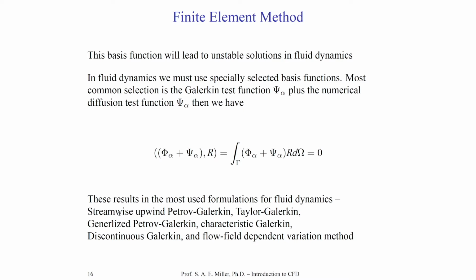That means that it essentially reduces to a stencil which has upwind bias. That is, there's more grid points or information in the equivalent finite difference approach in the upstream direction, that's the direction where the fluid's coming from, relative to the downstream direction.